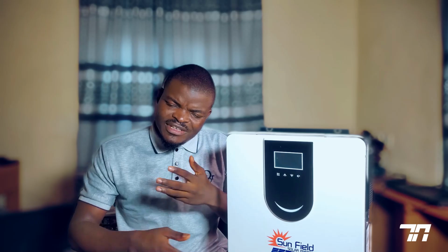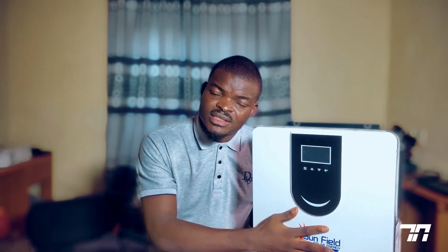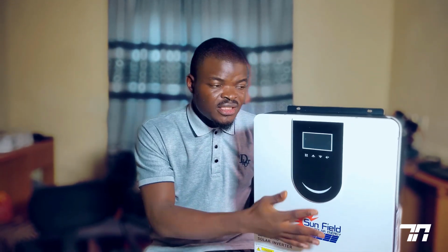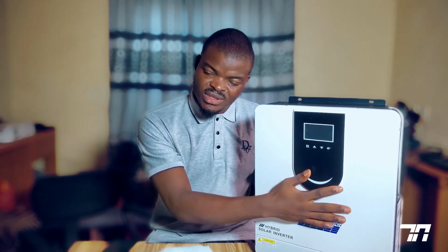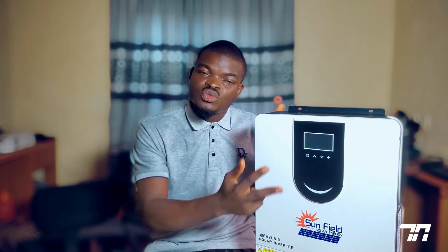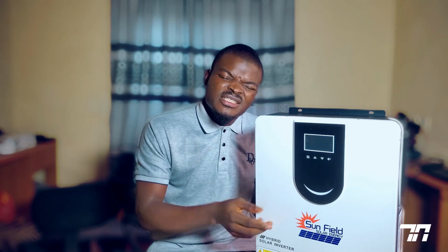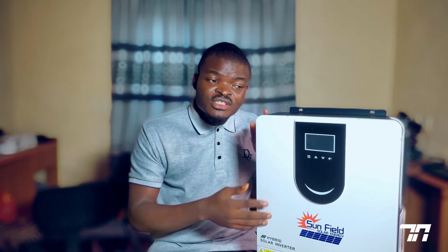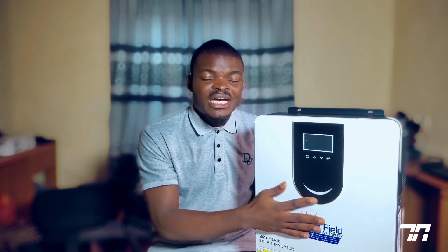And what's the advantage of having a high charging current? If you have two batteries, like this one now, this one uses two batteries. If you want to add to the battery, it gives you the opportunity to increase charging current, because the default charging current that comes with it is 30 amps. Now, that 30 amps is to charge two pieces of battery. When you add two pieces more to the battery, definitely you have to increase the charging current, which means when your battery is now 4, your charging current should be 60. When your battery is 6, your charging current should be 90. So you can use about 6 pieces of battery with this, and this inverter will still be able to charge it conveniently and to charge it full.